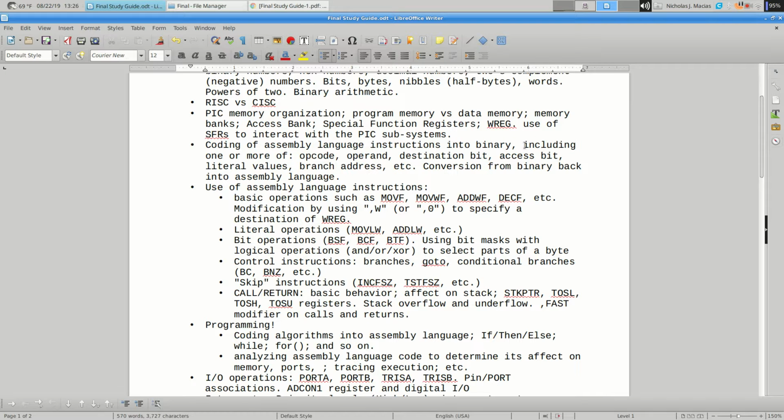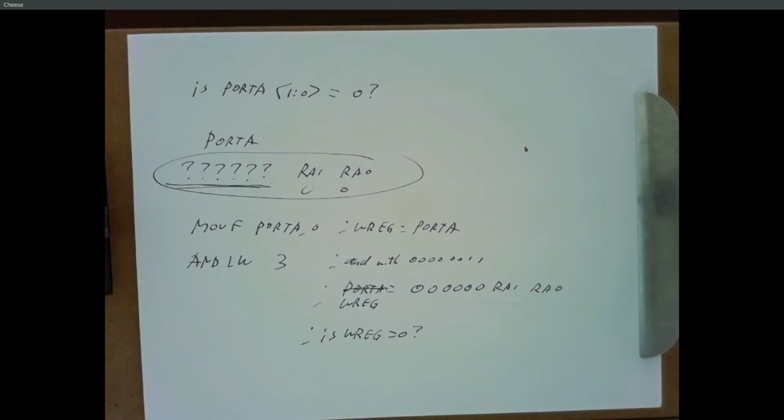Oh, okay, so that could have been, like you said, 3 instructions before, right? A no op doesn't affect the status. So if I increment a file register and then I do 25 no ops, then I say BZ, it's checking the 0 bit as a result of that increment. Yeah, 1 minus 1 would be it. If I did 1 minus 1, then the 0 bit would be set. Okay. So then if I did BZ, it would branch.